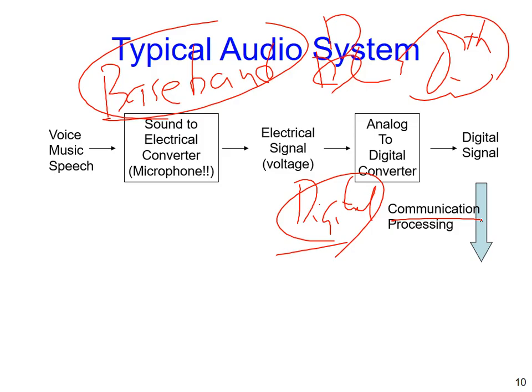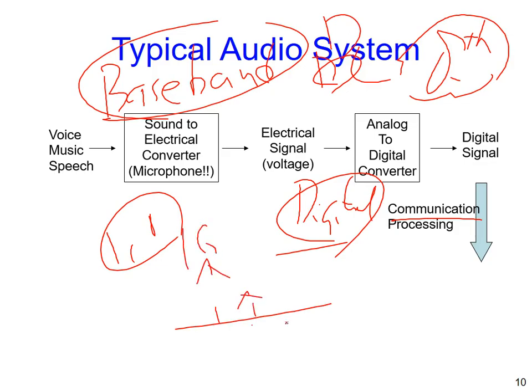Never mind your mobile phone. Digital communication only means the content is digital. But how about the physical RF signal, fully in analog? If you transmit 1 and 0 directly into the air, then according to Taylor's expansion, you will have a lot of harmonics. For example, if you transmit at 1 gigahertz, then you get 2G, 3G, 4G. Wow, you will destroy all the other transmitters in the air, interfering with each other. It doesn't make any sense.